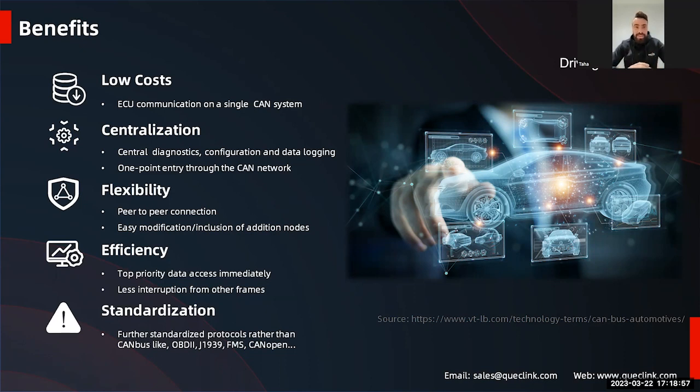Imagine that each ECU needed to connect with every other ECU using, for example, analog signals. Imagine how much wire we would have inside the car. Our car would be very heavy and costly, with a lot of errors and damages, and even very dangerous for a human being, right? So it simplifies everything, gives us low cost, low errors, low weight, and this is a very good solution that we can consider.